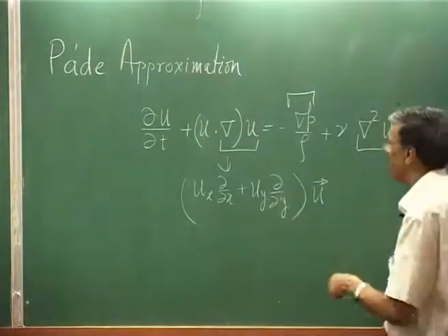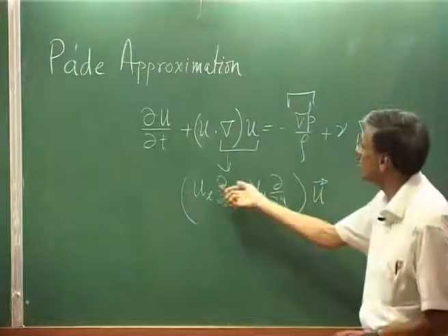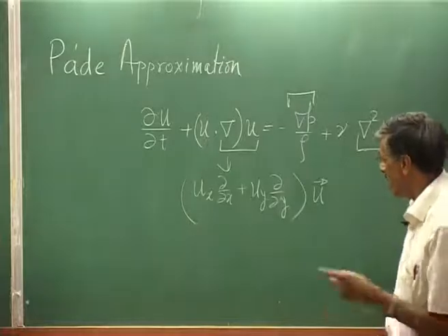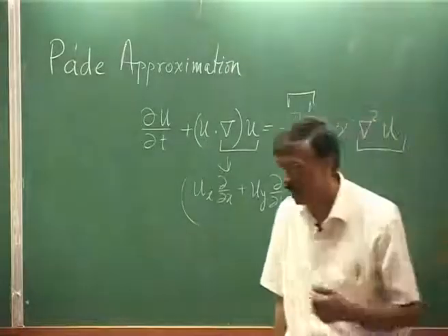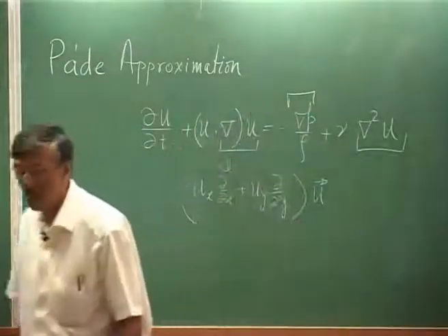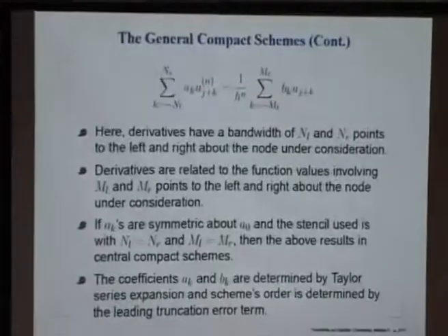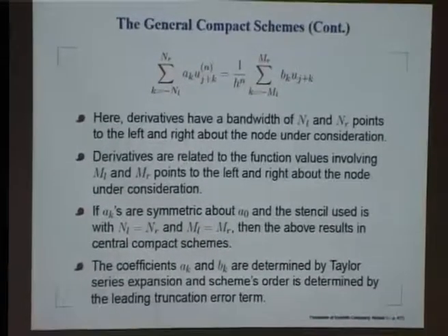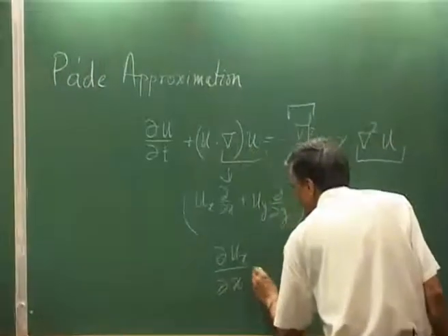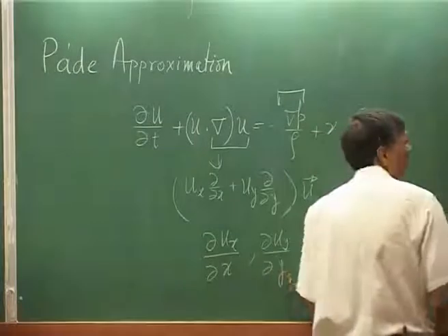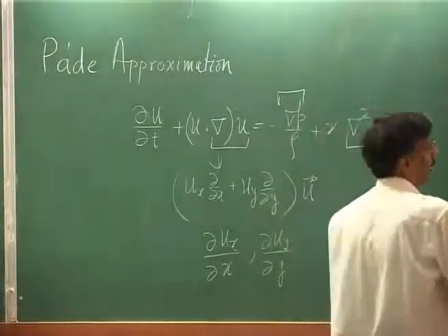Now, earlier what we did in explicit method, we specifically wrote those derivatives here, del u x. But here, instead of going through that route, we propose to use this kind of a functional relationship in evaluating the derivatives. So I could set up methods by which I could calculate this kind of derivatives a priori by using this equation given here.